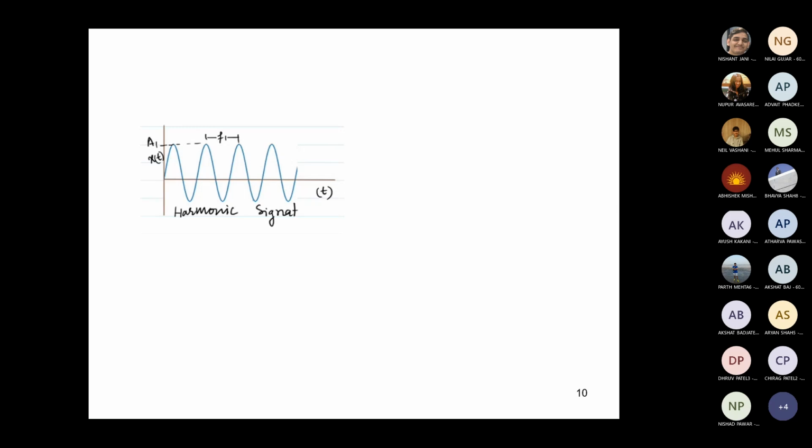So the fast Fourier transformation is basically an inbuilt mathematical function. I am not going to dwell on how it does it. I have already explained the theory, and I am not going to explain the programming logic because that is inbuilt in MATLAB. Now if I apply a fast Fourier transformation to this signal, what I will get is frequency on the x-axis and amplitude on the y-axis. It gives me the maximum amplitude for each corresponding frequency for this particular harmonic signal.